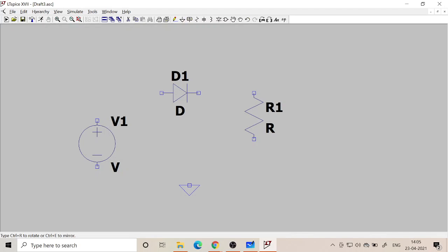If you apply 2 times, 180 degrees. If you want 3 times, then 270 degrees. So depending upon whichever way you want to place it, you rotate it, and then wherever you want to fix, you move it and click one more time, it will be fixed there. So similarly you can shift this also.